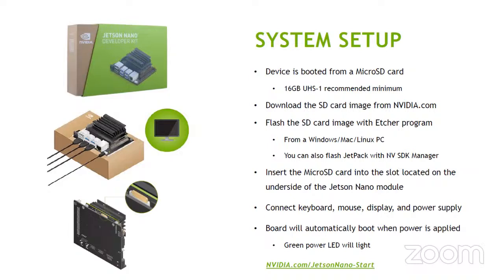The micro SD card should be a minimum of 16 GB, because the OS itself is 7 to 8 GB, and once you write it, you need some space for your system, whether you're going to save files or videos or data sets, or install extra packages. Most of the packages that we use in deep learning, like PyTorch or OpenCV or Keras, are not built into the Jetpack OS. So we have to install all those things externally, manually.